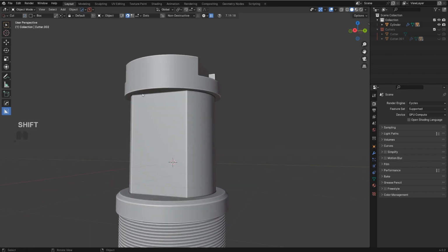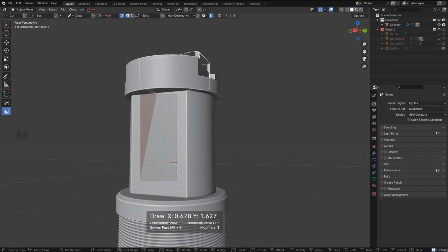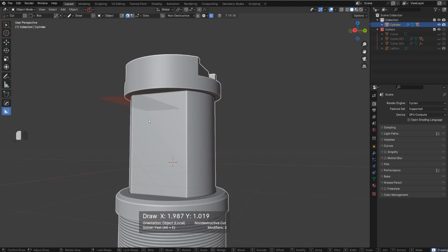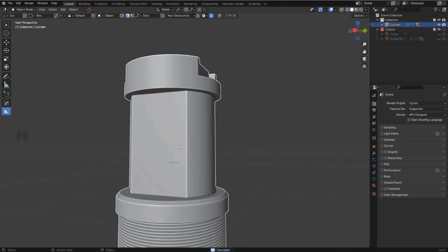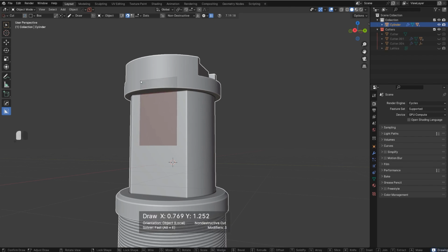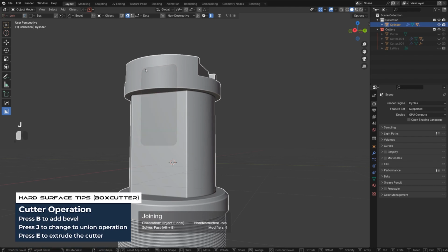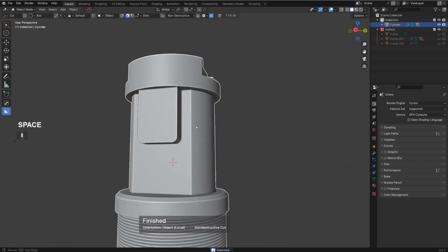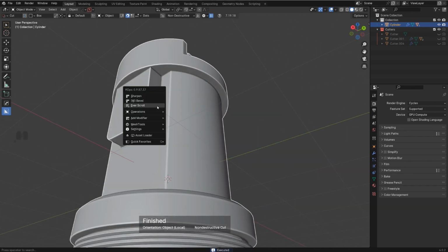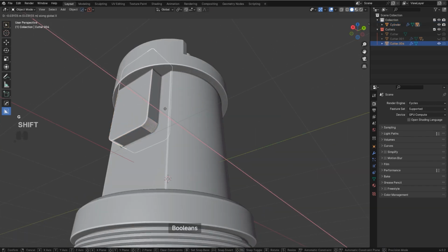Here on the side, we could create another large element. So select this and run a cut here like that. Maybe a little bit larger. Maybe not as deep, but wider like this. And then bevel it and press J, E, and extrude it in here and the other way. Come on. And apply. Are we looking? That's a little bit too aggressive. Let's move it in. There we go.